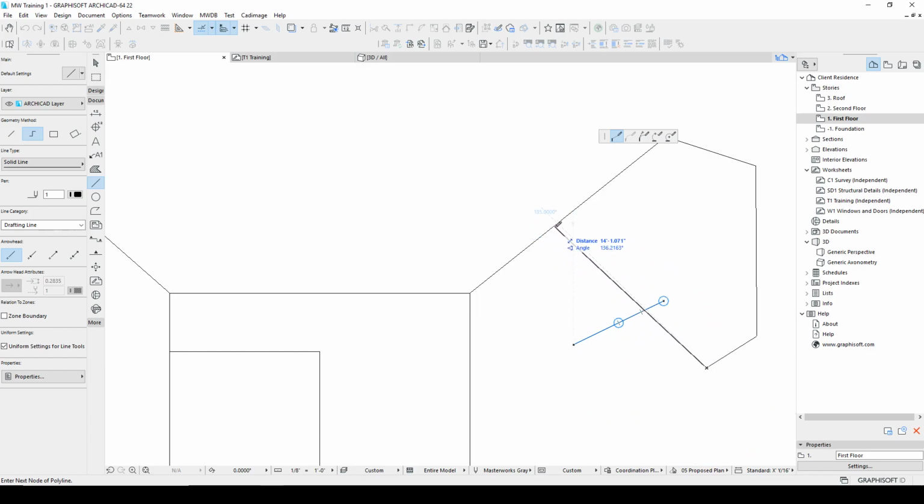And then the other option, you've got to hunt for it a little bit, is perpendicular. There'll be a guideline that does the same for that. Once we are holding it there, I'll do that again, and I get the perpendicular sign. Now all these guidelines, or snap guides, are making it complicated for us, so I'll turn those off so they're not interfering. But that's the perpendicular. From this corner to up here, that is a perfect square 90-degree corner. So we can move from endpoint, along the line, midpoint, perpendicular.